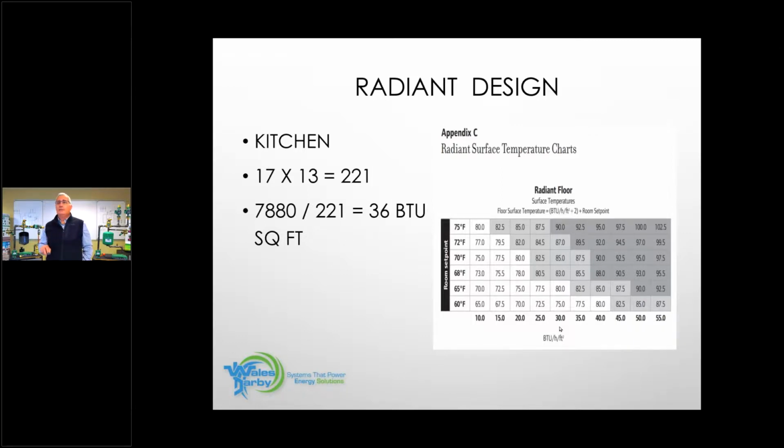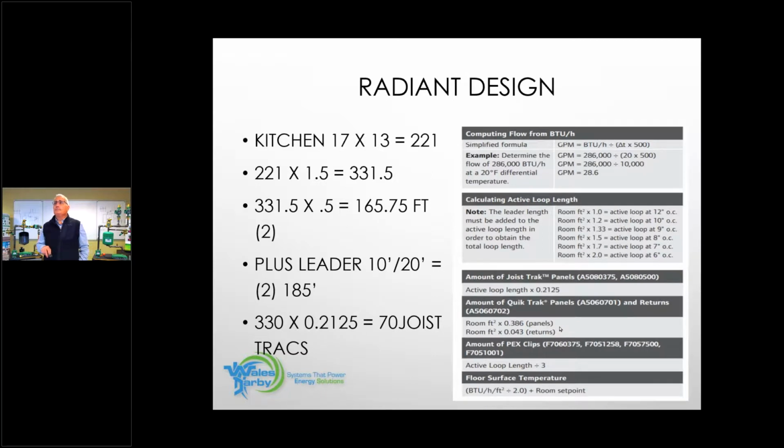So as we're waiting for that, I'm going to move on. They want to know what you would do with the unfinished basement ceiling. I think that's right where you're going. So, okay, my tubing is going to be under there. My joist track plates are going to be under there, and under radiant heat at all times. I don't care what kind of install it is, you have to put insulation.